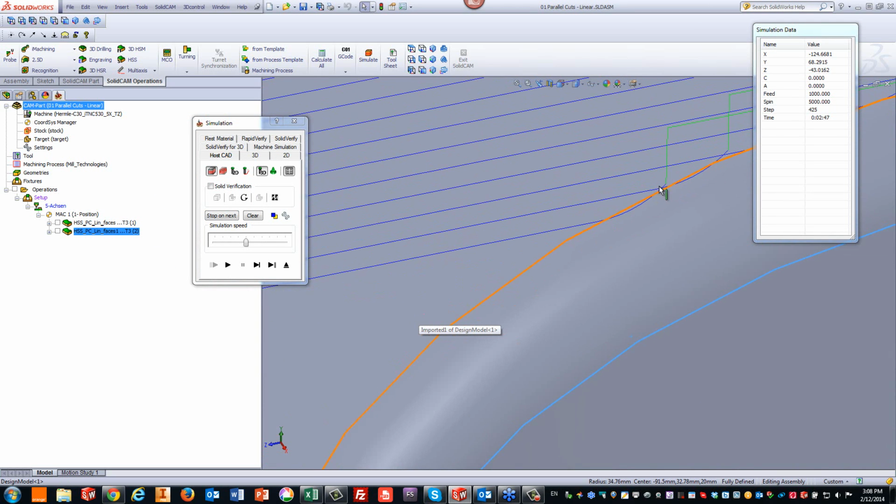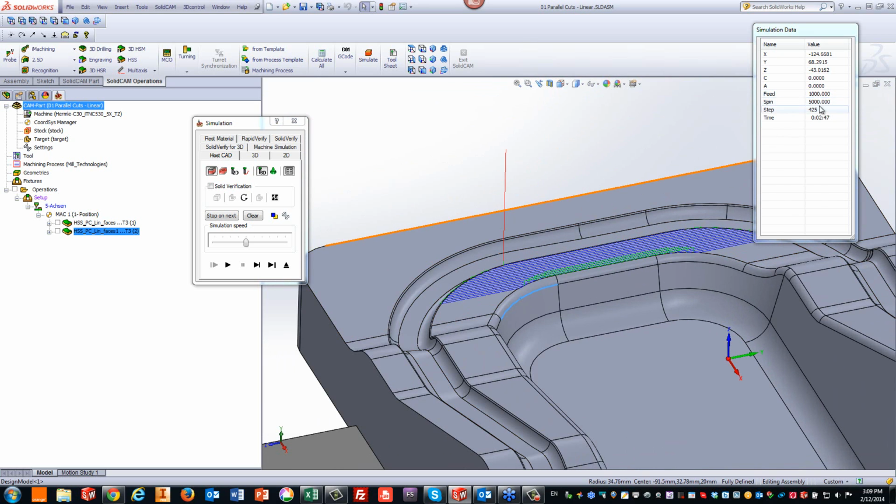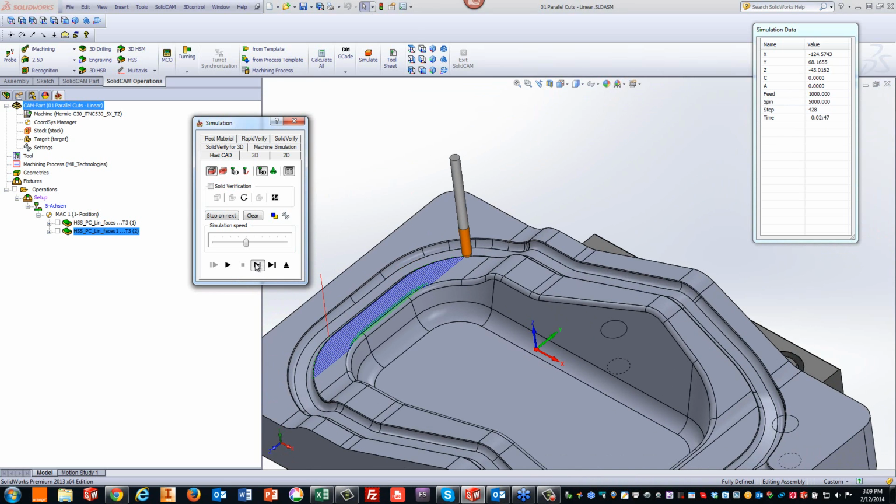You see it retracts with the arc, then goes up just a little bit to the safety distance. But now look what happens to the feed when I'm working in that particular area itself. Let's continue now. I'll do it one step at a time. As you see, it's going across right now. It's at 1,000. It goes up. Now when it gets to the top over there, look what happens to the feed. The feed automatically changed now to 4,000. And now every single time it works across the top over there, it's going on that faster feed, if I want to do it that way.